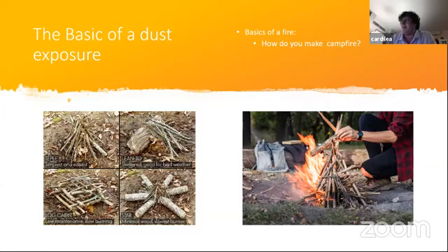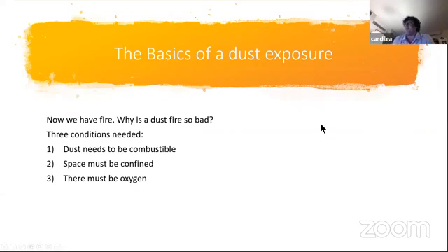So yeah, dust basically is just very, very small stuff. It burns extremely easily because it's very tiny. If you think about it, if you hold a match to a log, it's not necessarily going to light. Hold it to a twig, it's going to light pretty quickly. The smaller you go, the easier it is to light, and the faster it's going to burn. That's the base of a dust explosion.